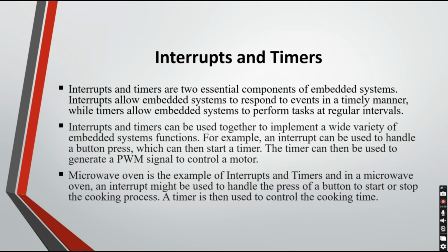Interrupts and timers are two essential components of embedded systems. Another example of a communication system that uses a timer is one that generates the start and stop bits for a serial communication protocol. When the timer expires, the microcontroller generates an interrupt to handle the next bit of data.